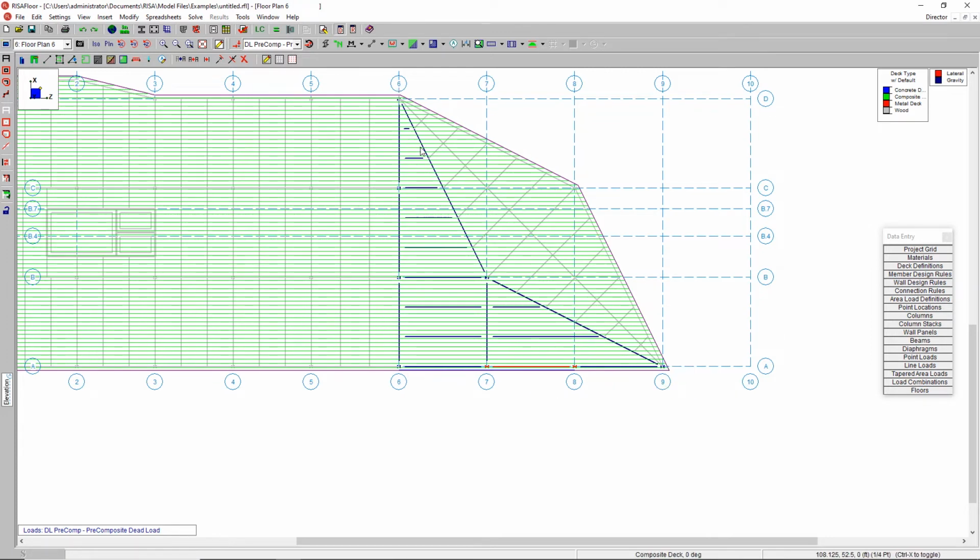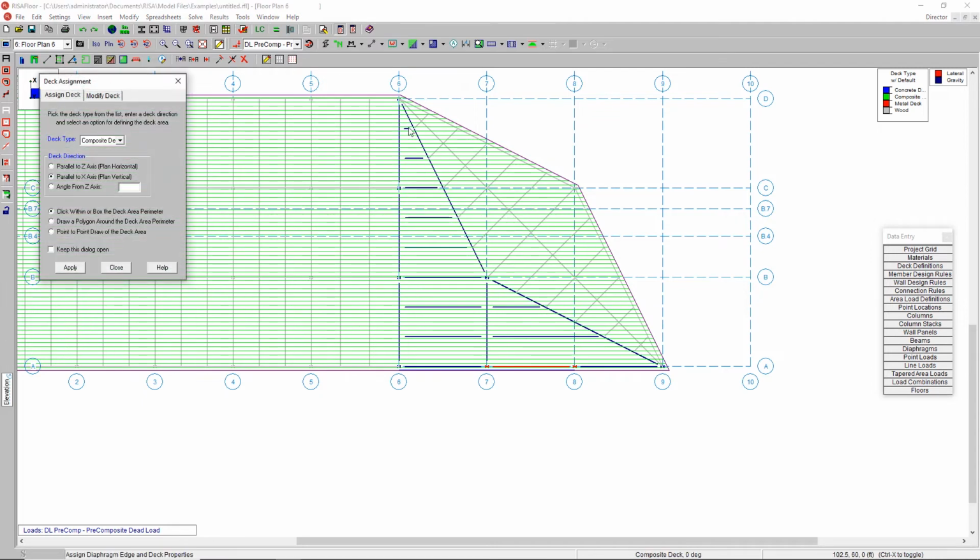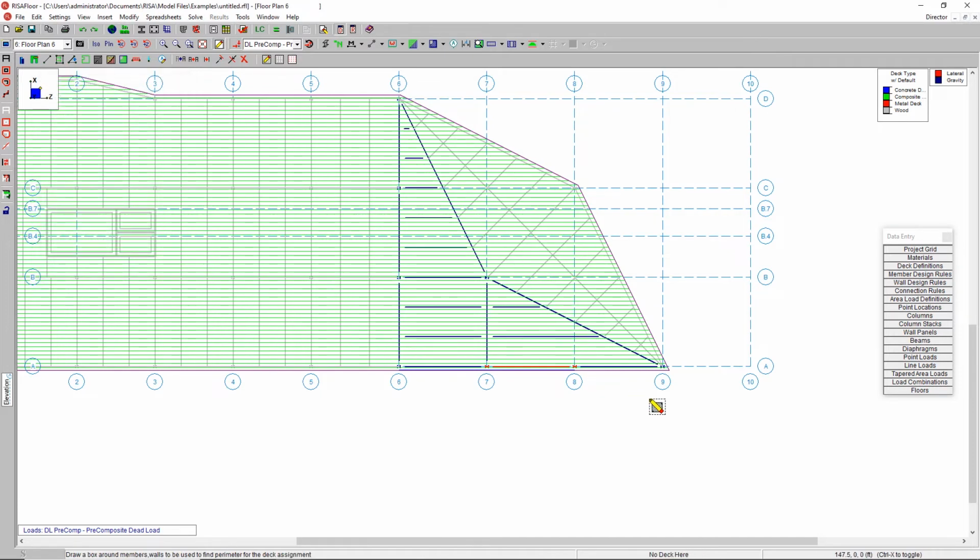Like I want a deck internally, and this is the outline of that area, so I can use this deck definitions that way. Just makes it easier. You can click in the bays, but I don't like doing that. I think it's much better to do it as a whole like this, so I can call out this whole area, and now it's a fully connected polygon. Makes it a little bit easier under the hood, so I do recommend that.